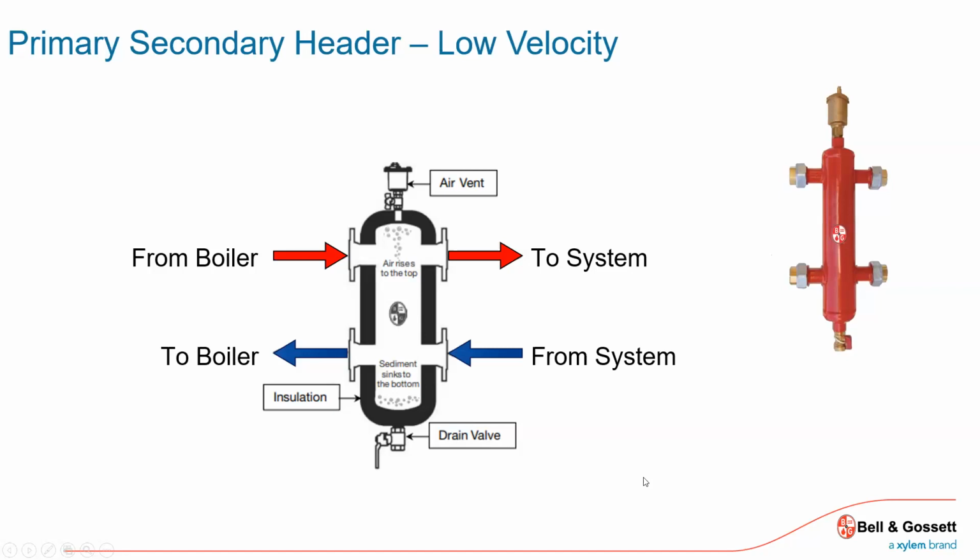There's a bunch of different manufacturers. We're one of them, Bell and Gossett, but there are others out there. It really was promoted with the boiler plants. So 2, 3, maybe a multiple boiler plant, connecting it to a distribution system. I've got to separate the air anyway. That's my hottest spot. Why don't I use my primary, secondary connections and my air separating devices all in one? And that's how it came to be.